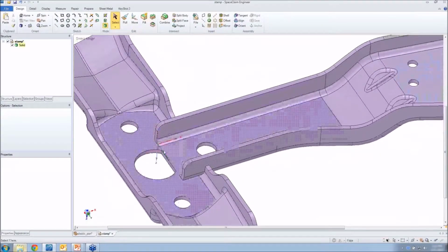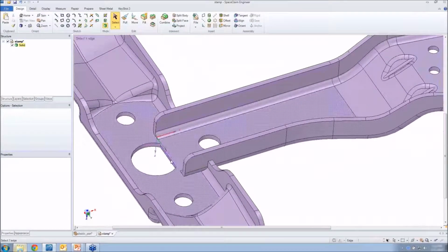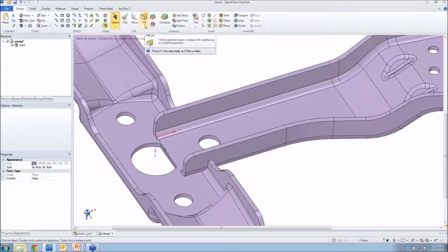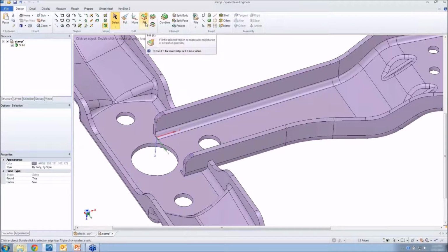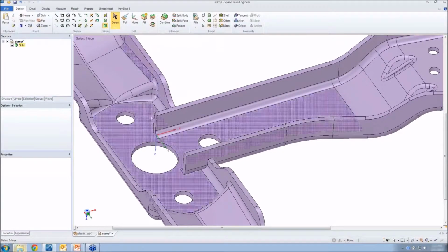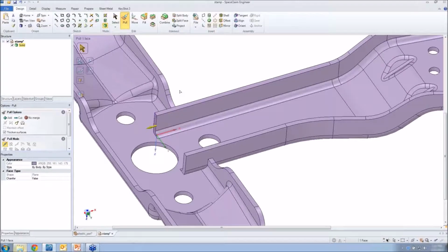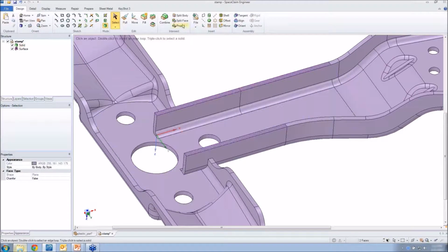Very easy to do. Also, if you remember just a second ago, I took the two models, moved them close to each other, and encroached on that circle. That's not a problem. If I moved something too far, I can always fill in that edge and complete the circle. It's that simple to do. And maybe get rid of some rounds in here and actually flush this thing out to get it the way that I want. You know, reusing data is so important in not having to reconstruct sketches to get exactly what you want. I'm taking a face and just throwing it somewhere in the mix. And the sole purpose of that is to create some kind of a reference area by which I could chop up a face.